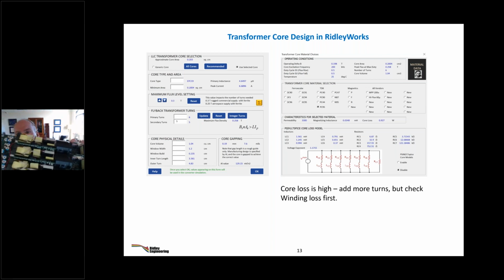And basically when you look at the boards of the final designs, you only see one thing, and that is magnetics. Okay, so choosing the circuit element is step one. That's the easy bit. Designing the magnetics themselves is step two. That's where it gets more complicated, but that's the meat of the problem here. So like everything in power electronics, it's all about the magnetics. Control is control, and yes, that's important, but we can control almost anything these days. Magnetics are what you need.